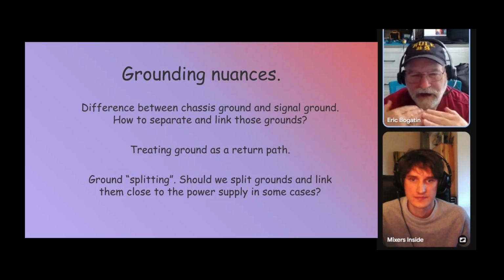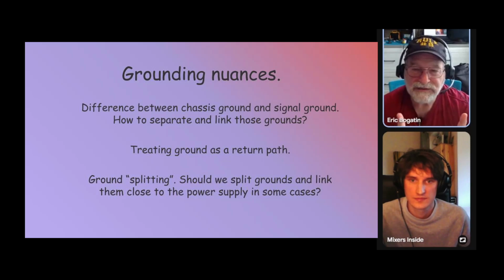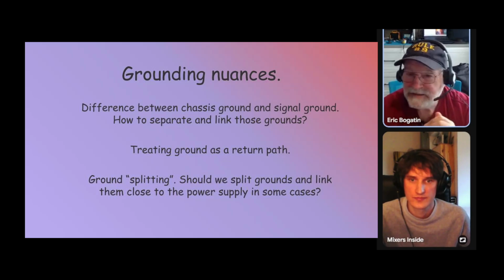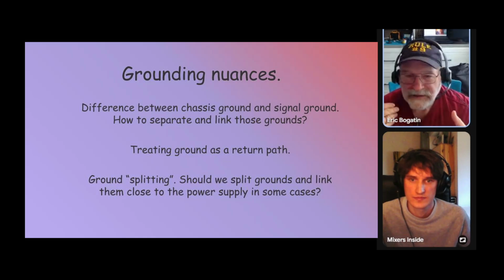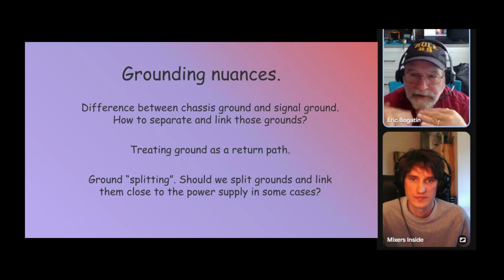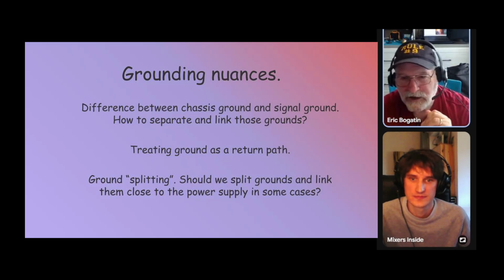And so I go through the example of measuring it with a scope so we can see how much resistive crosstalk there is between the aggressor line and that poor victim line sitting next to it. It's measurable with the right techniques. And then, just like you said, I cut the ground plane so that we isolate the DC currents. We still have capacitive coupling and inductive coupling, but at low frequencies those are really small. By cutting the ground plane, we isolate the return currents in that ground reference, and the crosstalk goes away. It is below the microvolt range, which I can't measure with the scope.